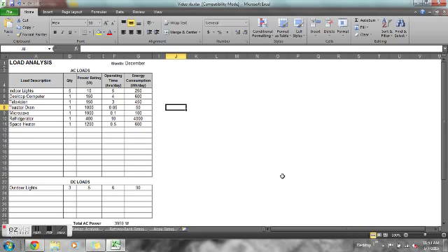The third step is battery sizing. In this step, you estimate the battery storage size based on the desired autonomy period and the maximum and average daily allowable depth of discharge. The fourth step is sizing your PV array. You want to make sure your PV array can supply power to the loads and charge your batteries during the critical design month.